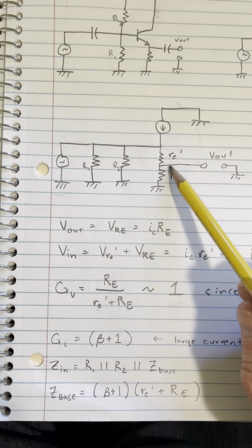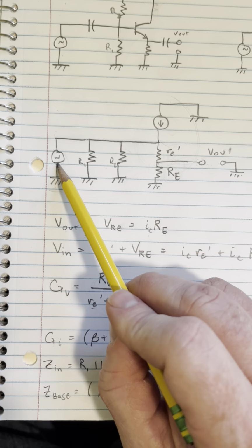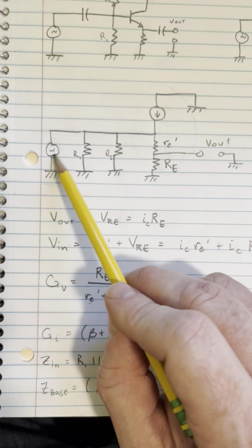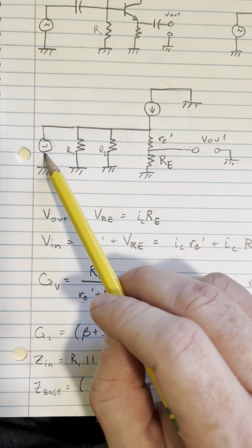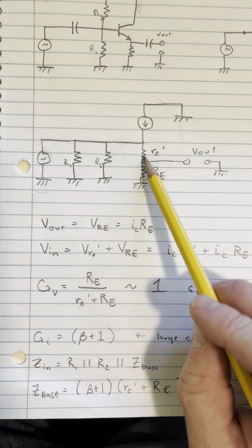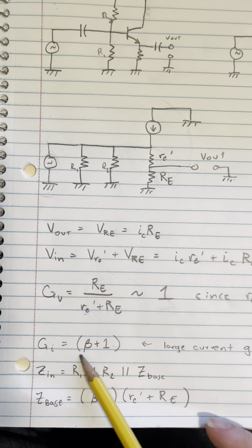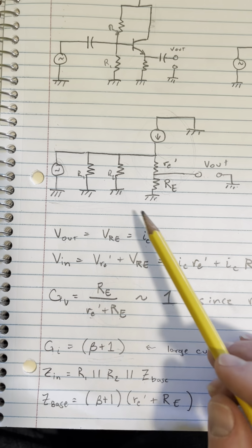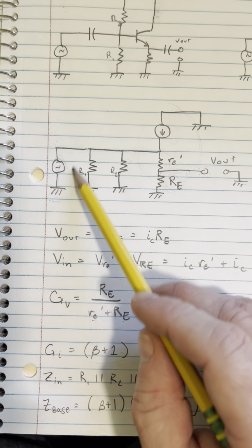The other side of the transistor reproduces the voltage on this side, but you can have a very, very weak power supply generating your signal, something that cannot provide a lot of current. But on the other side, you can reproduce that voltage with a lot of current behind you. So with a very low power device on the input, you can reproduce the same voltage with a much larger power on the output. And that's the key